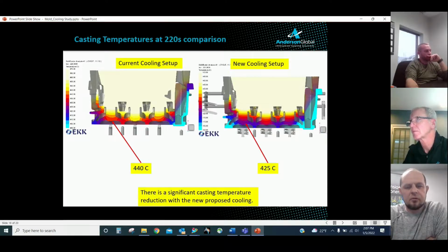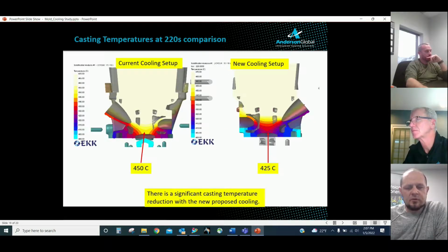Here you're showing a cross-sectional area of both setups. Again, showing that the added cooling made a significant difference, and it dropped the temperature in the combustion chamber area, not only in the combustion chamber area, but in the whole setup. Here's another section. You can see the spiral cooling at the bottom. So when you look at the scale, you see how much hotter the center of this combustion chamber area is. You're seeing yellow and dropping the temperature here into red. Yeah. And that's how we were able to shave off those 60 seconds, but structurally did not change the casting.